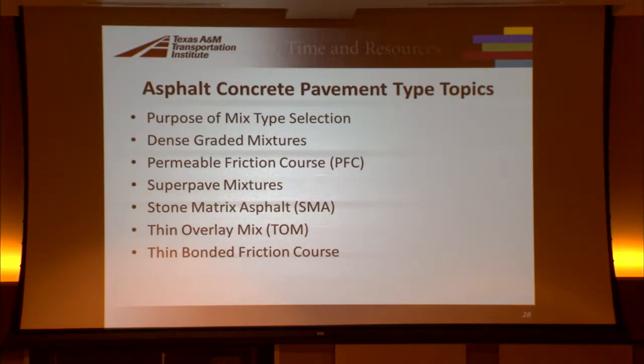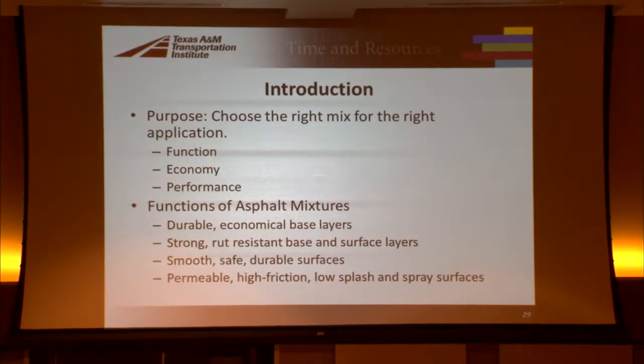Things don't change as much as you think they would. So I'm going to talk about these various courses and some of the experiences I've had and some of the observations we've had. Obviously, the purpose is to choose the right mix for the right application. You're looking at function, ride quality, skid resistance, and noise. Economy, preferably using locally available materials, and obviously performance. You want to have durable layers, rut-resistant bases, and so on.